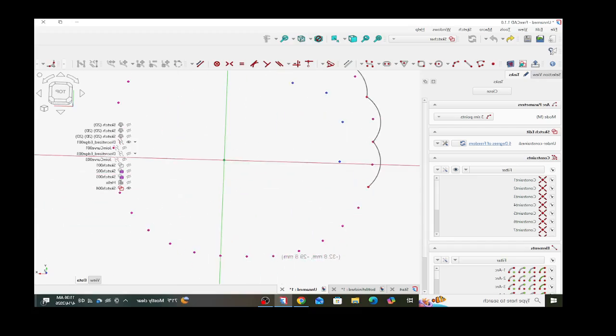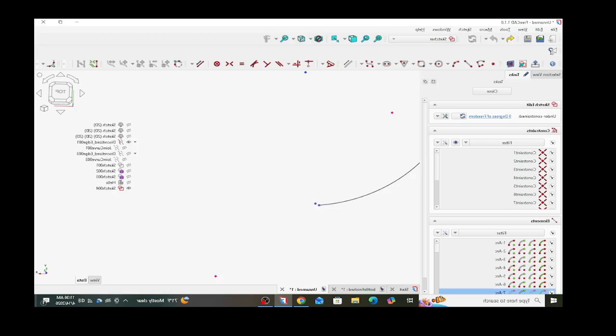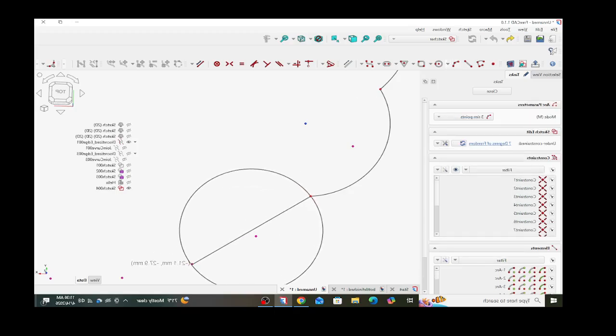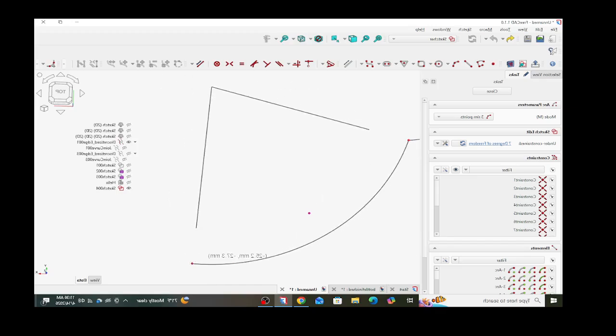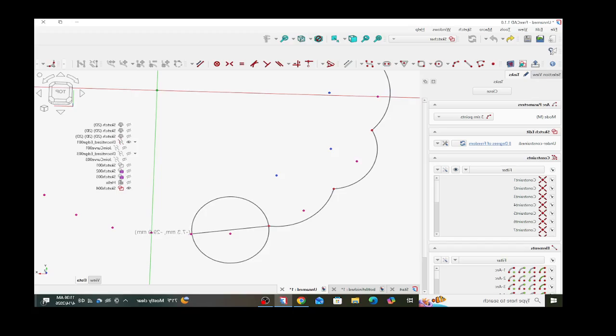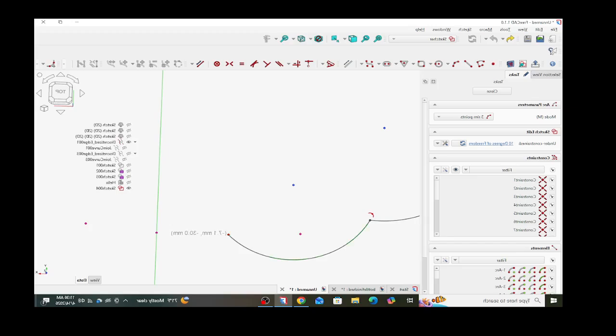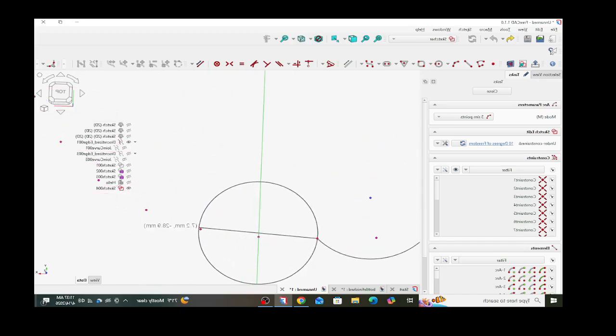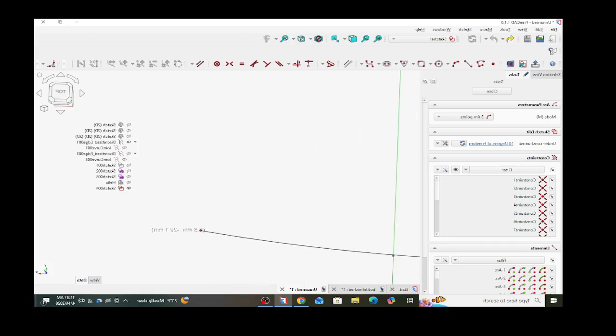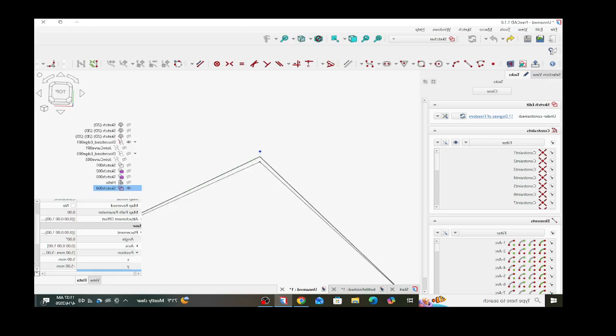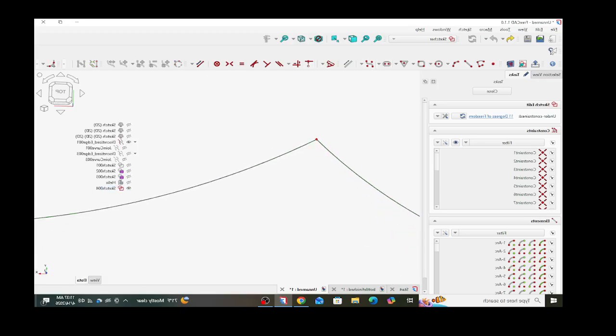You'll know if you miss the point because you'll get a near tangency. It won't be fully constrained when you're through. You'll get near tangency on the, or open wire, etc. on your point. I need to go into settings and change my pick radius. So just zoom in and make sure these are tangent. I think that's going to work.